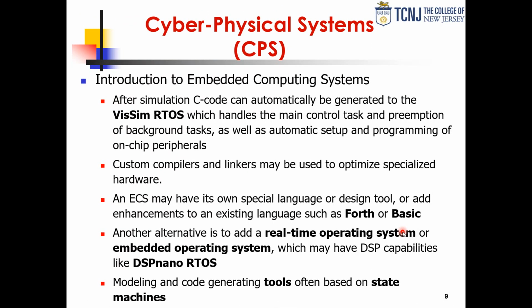So again, RTOS, very important, and a good example is the DSP Nano RTOS, if you have DSP type applications. It's a very small, straightforward-to-use RTOS that you can use for DSP signal processing types of applications. We tend to be simple when it comes to the operation of it, because you're doing a very specific algorithm, and what changes is the stream of data that you have to process. The data stream is a lot, but the actual processing on that data stream tends to be very specific. So that takes us to the paradigm of multiple data, single instruction type of computing.